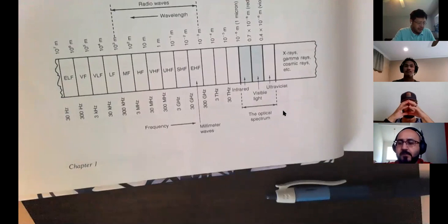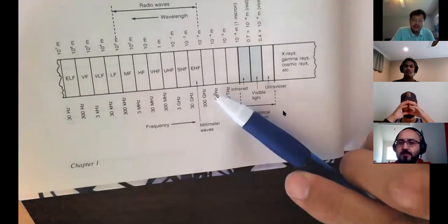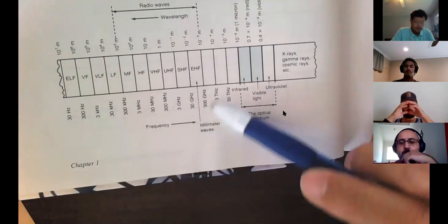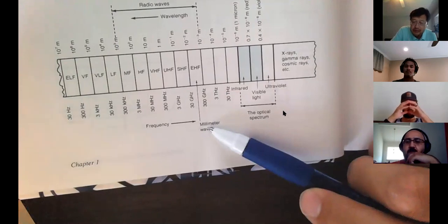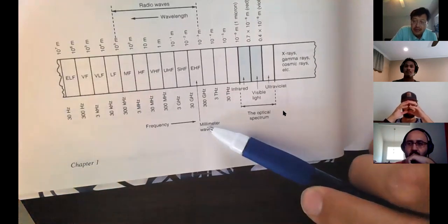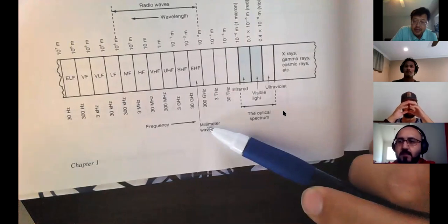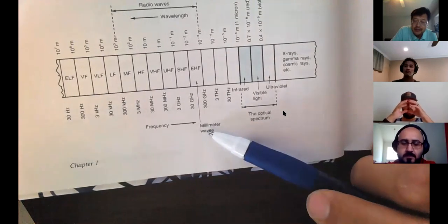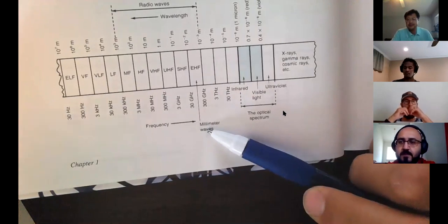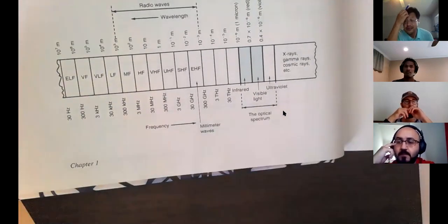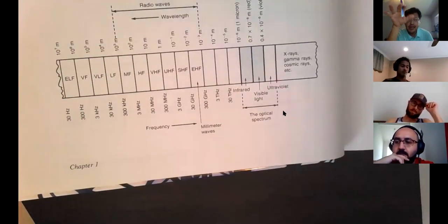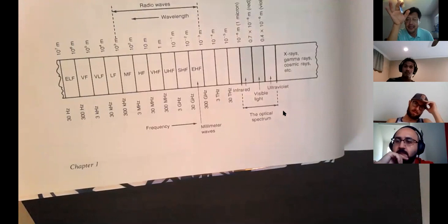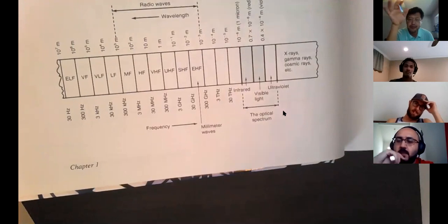So each has advantages. What is the disadvantage of the millimeter frequency? The disadvantage is it only travels in line of sight. It only travels a short distance. So for 5G millimeter wave to work, you have to have a lot more antennas. Fortunately, each antenna is a small size, like a suitcase, so you can put a lot of those.